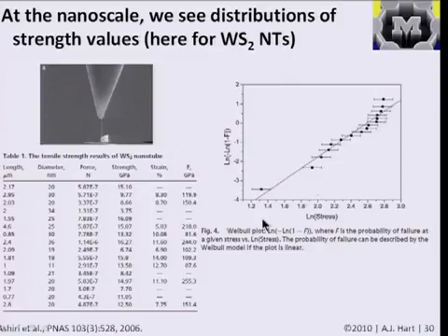So as I said before, every material has a statistical distribution of strengths, and here they're able to plot out in a relatively organized fashion a distribution in the probability of failure as a function of the applied stress. So F, the failure probability, is basically the probability that a material will fail at a stress equal to or less than the applied stress. So if you choose a stress which is really high and that it's going to make all the materials fail, then your probability of failure is 1. If you choose a lower stress, then your probability of failure might be 1/2.